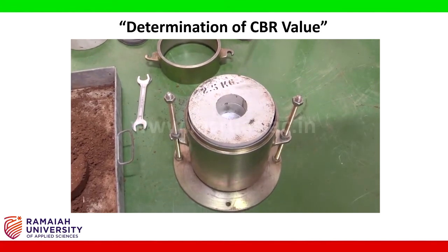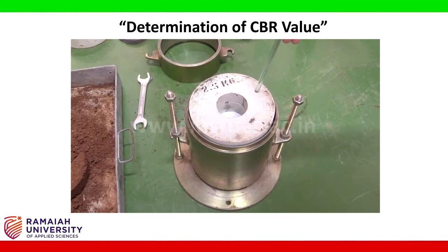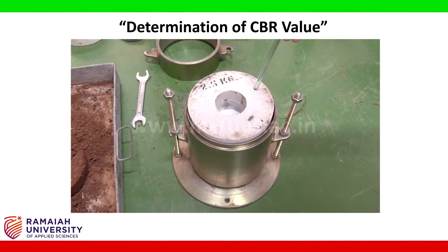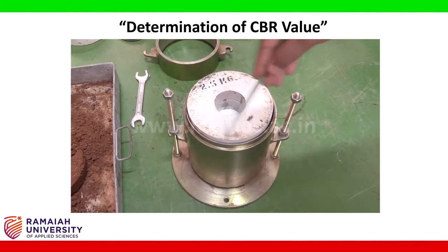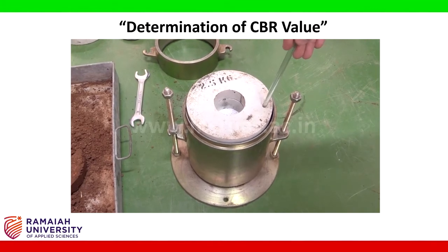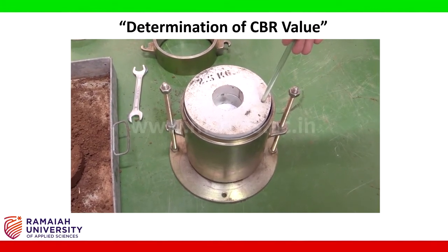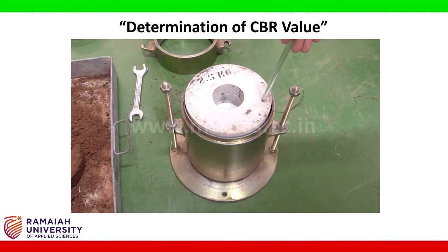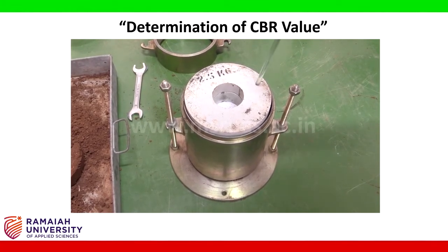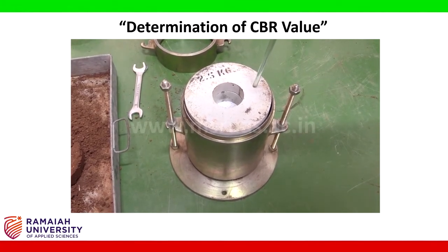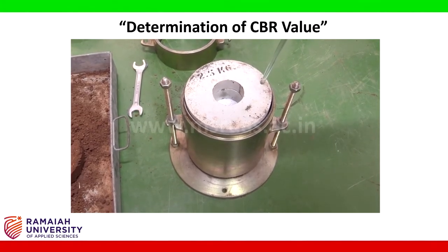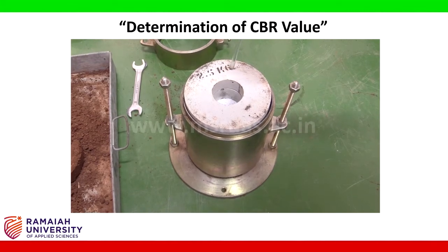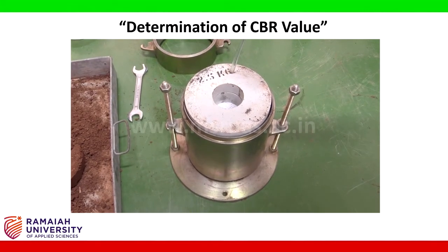We can test the specimen in the dry condition like the way we have prepared the specimen now, or we can have a soaked CBR by soaking the whole specimen along with the surcharge weight in a bucket of water, which we call the soaked CBR test. So we are concentrating on the unsoaked CBR test, and hence we need not soak the specimen before the testing process. Once the surcharge plates are placed, it is now time to test the specimen.